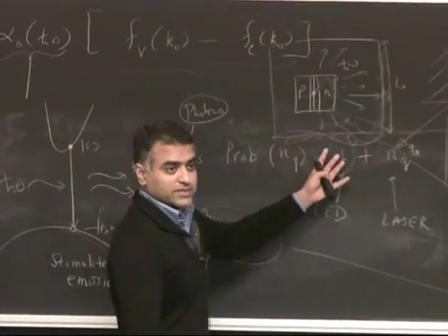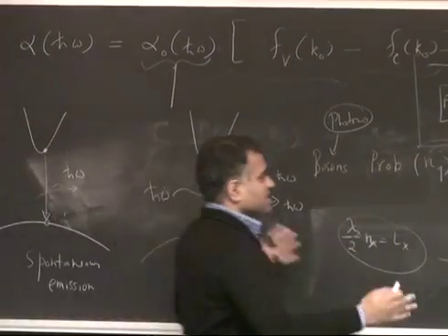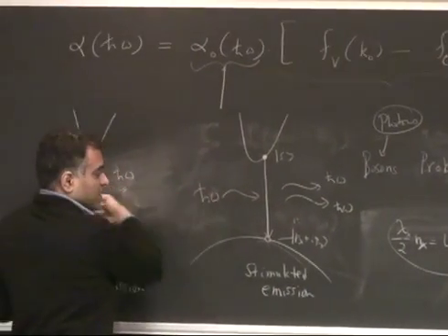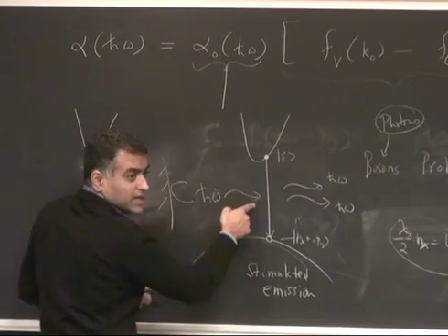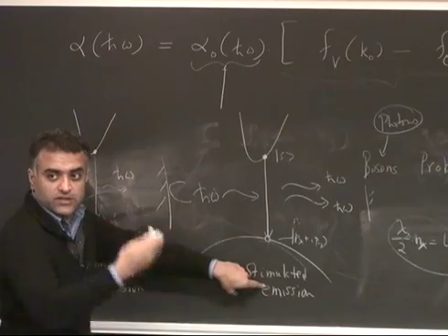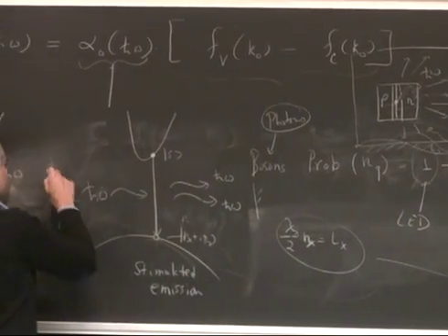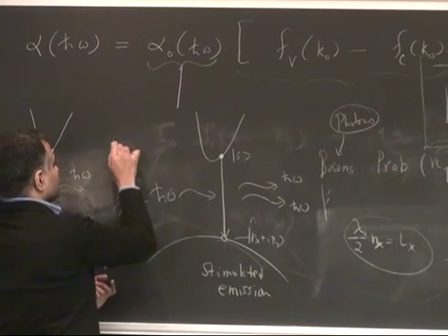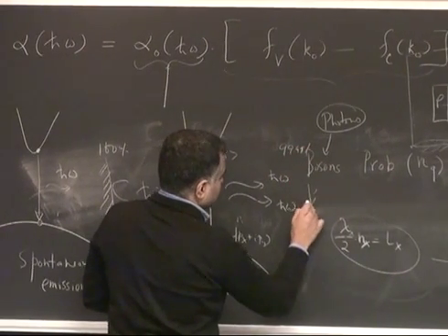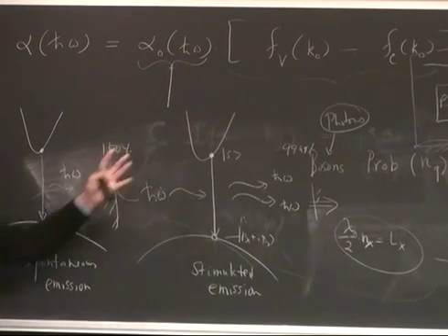Essentially, the game is to have mirrors around it. The mirrors really make this possible, because light is generated inside the quantum wells, and then it wants to get out, but you bring it back. Let's say light wants to get out here, but then you reflect and bring it back, and then you reflect again, bring it back. So you're continuously stimulating the emission now. That's how you're increasing this N_q now. So you typically do multiple passes before it gets out. Ideally, one mirror is close to 100%, though it's never quite 100%, and the other maybe 99.99% reflectivity, and then the laser light really comes out from this side. So a little bit of it is leaking out continuously. That's conceptually how you make the laser.